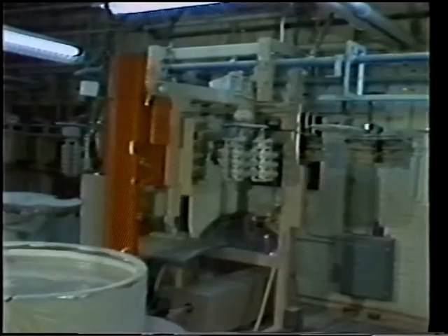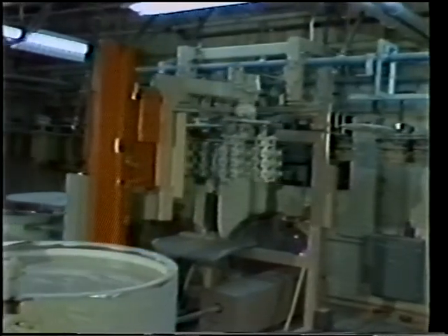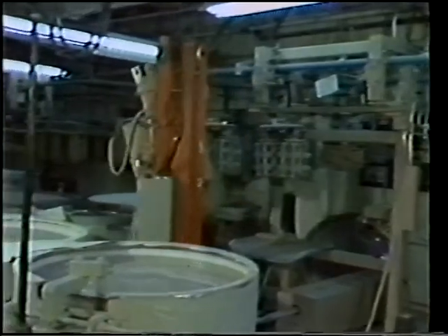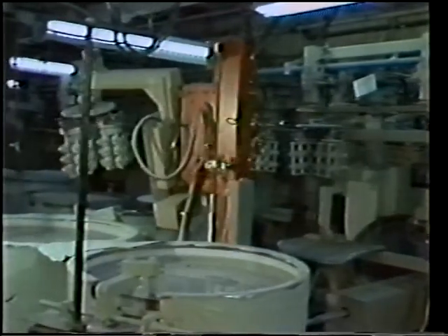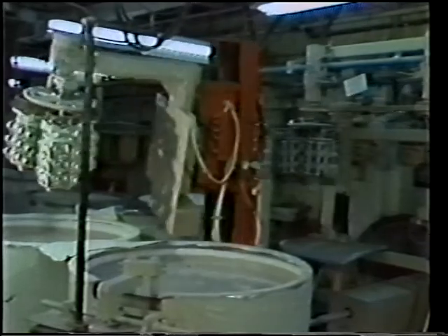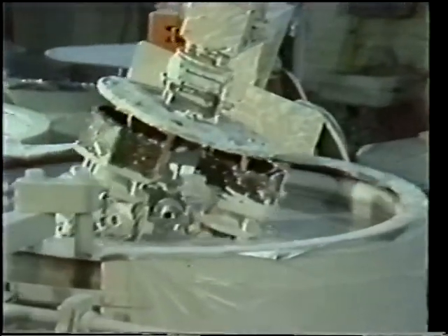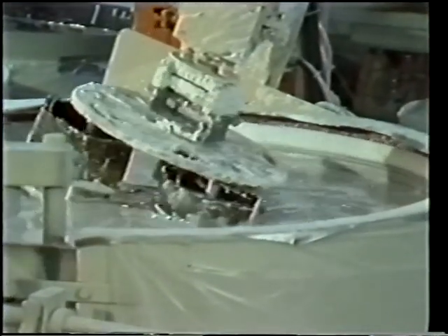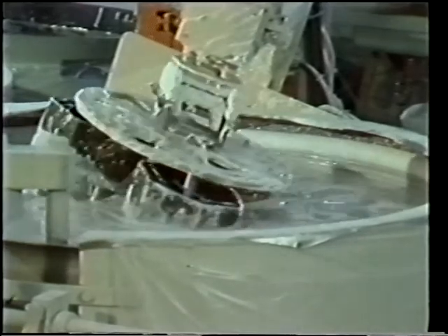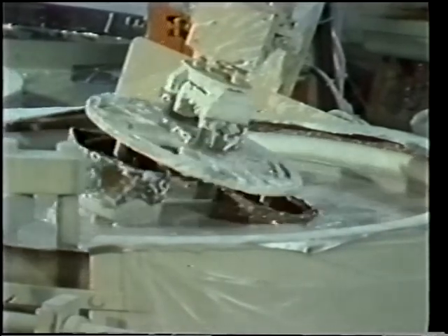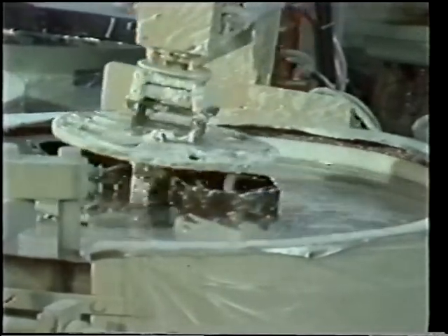After the cluster dries, a second coat of refractory is applied to back up the first. This is generally not as thick as the first coat and is usually different in composition. Refractory thickness and consistency is varied according to the particular application. Clusters are thus dipped an additional number of times to form as many layers as is necessary to achieve adequate mold thickness and consistency.